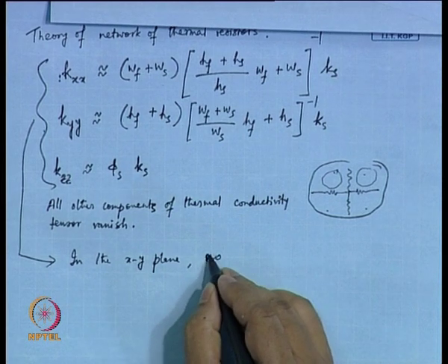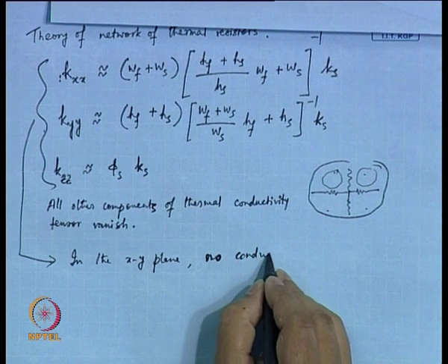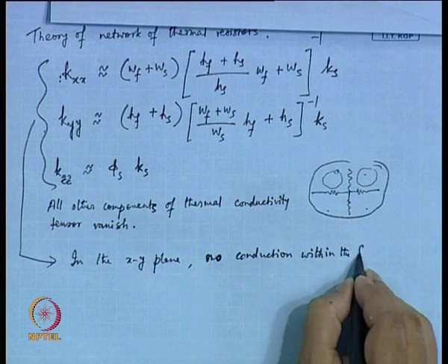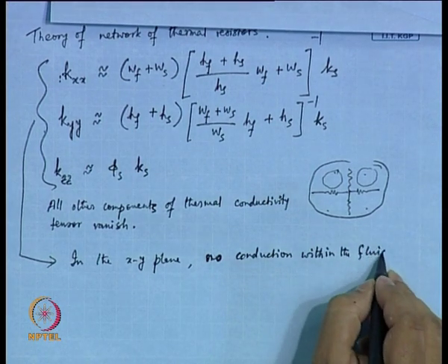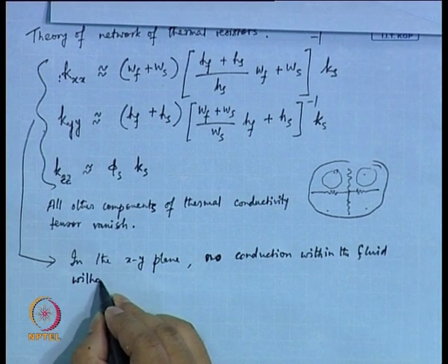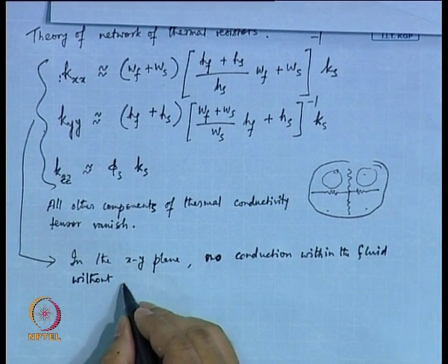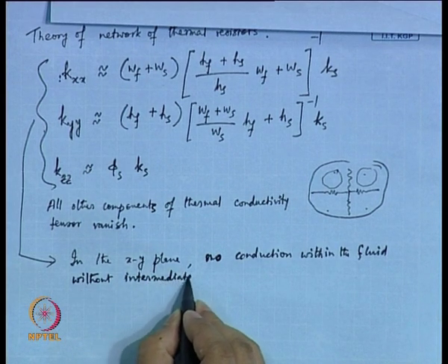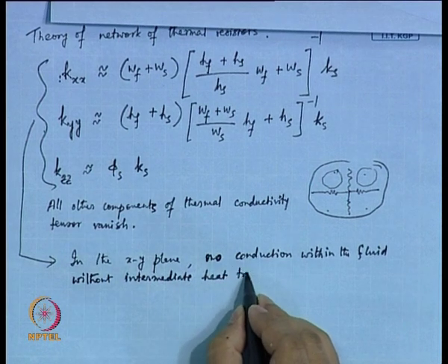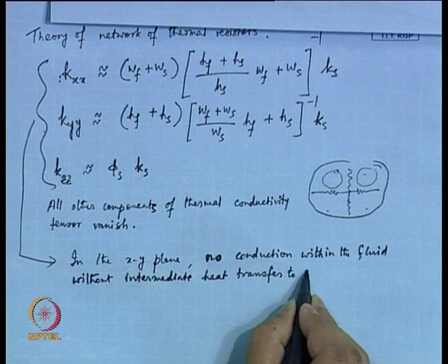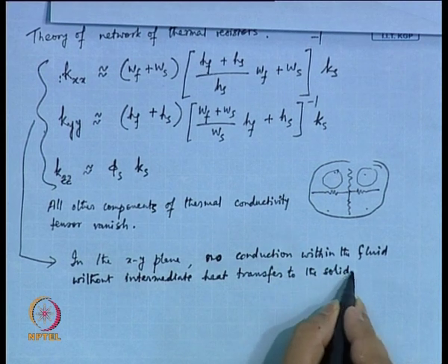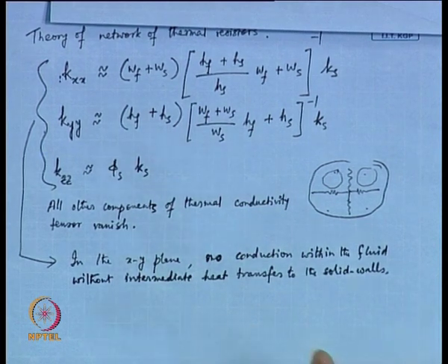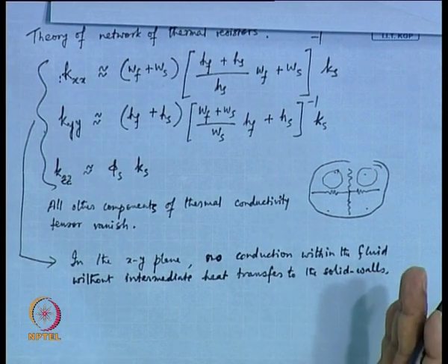No conduction within the fluid without intermediate heat transfer to the solid walls. So, this is something which you are basically considering very tacitly, that you have two channels side by side and in between you have a solid, right.